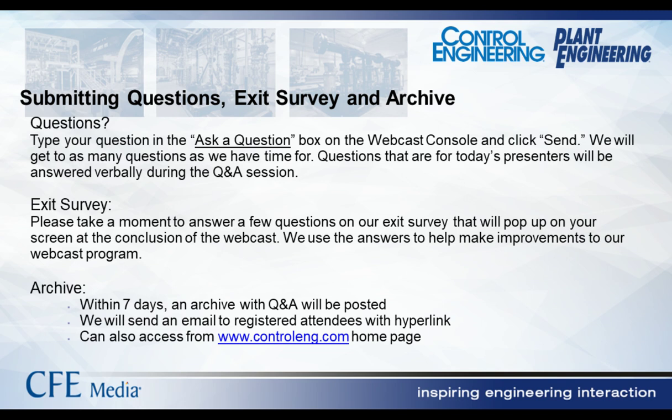A question addressed to Ryan. Who should be involved in a risk assessment? So risk assessment should involve the maintenance staff. It should include operations, so whoever's going to actually operate the cell, and it should involve the integrator, whether that's an external integrator or your internal integration team, and it also should involve somebody from the safety side of the business.